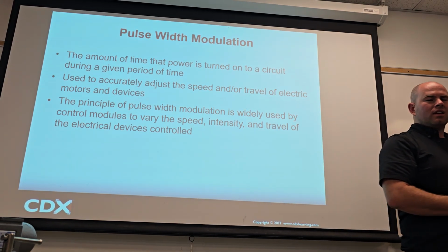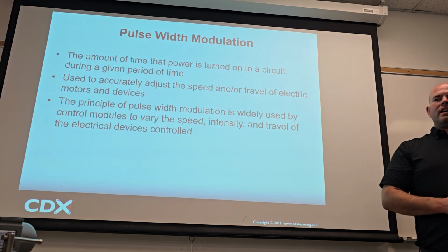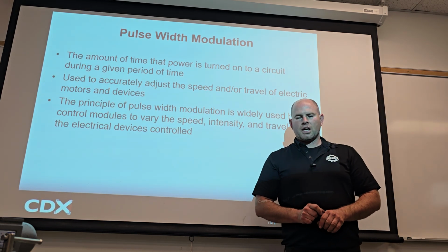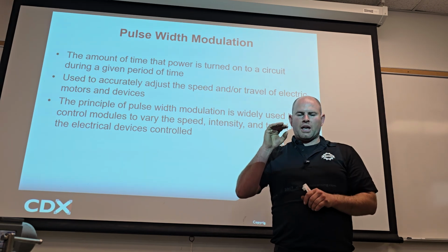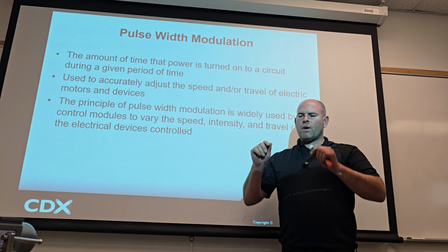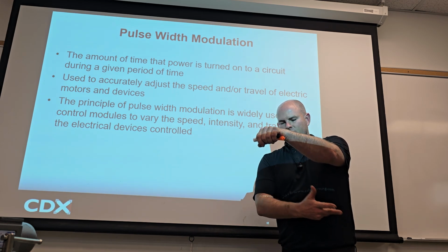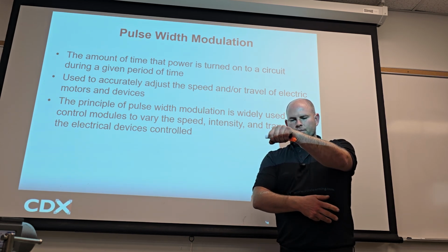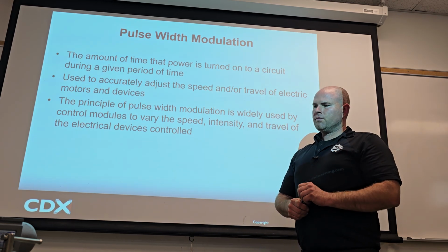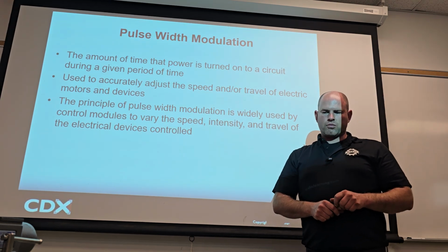I think I could explain that really well if I jump back to that transistor screen. The scan tool scope signal is literally just the transistor on and off time. Whereas if you actually go in with your scope and probe at the motor, you're seeing what it's actually getting. You're sampling the signal in real time. And I prefer real time because it's not processed information. It's just raw right then and there.